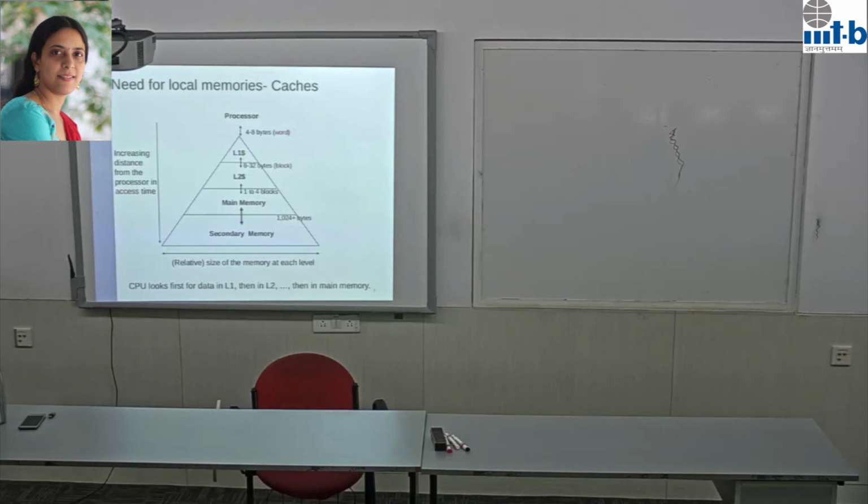The bus width would be based on the data size. If we are using a 32-bit data bus, it will be a 32-bit data bus all the time, and the access time will be with respect to that data bus. The data bus is really an interconnection on the processor or on the board, so that can't be dynamically changed. It will be fixed for a particular processor. So all we can change is the levels of caches and the sizes of these caches.